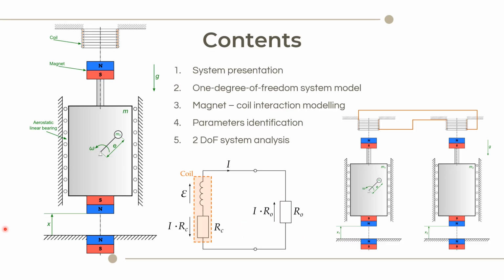Dry friction in the system can be neglected due to the use of aerostatic supports for accurate vertical guidance of the oscillator. The mass can be excited by a harmonically moving unbalance driven by a stepper motor permanently fixed to the oscillator.